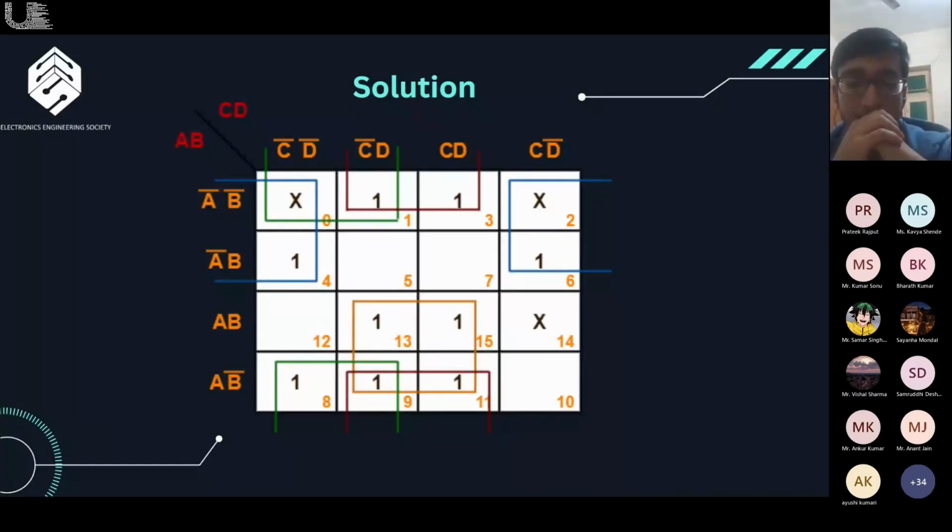Yeah, that's the point. Now we do not want to make duplets, right? If anything can be grouped, we start from wherever first you see if you can make an octet. If you can't, then you go for a quad. If you can't, then you go for a duplet. So here I can see that I can group 8, 9, 0, 1 inside a quad, right? So I'll go for a quad. So always remember, if we can make a quad, we have to make the quad. You do not make a duplet instead of a quad. So always start in that hierarchy: octet, quad, and duplet.